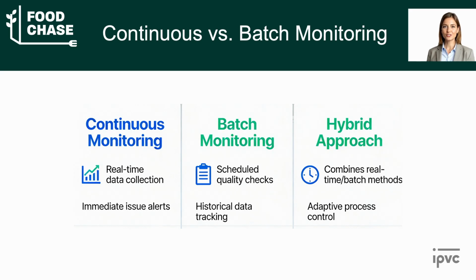The frequency of monitoring depends on the nature of the process and the risk. For a pasteurizer or a deep fryer where the product is moving quickly through a heat exchanger or a heated vessel, conditions can change rapidly, so we monitor continuously, perhaps every 5 to 10 seconds, and the system automatically adjusts or alarms if temperature drifts. For a fermentation tank where the product sits for several days at a controlled temperature and agitation, we might check the temperature every few hours or every 12 hours. Continuous monitoring would be overkill. For storage, we might spot check temperature once or twice per day.